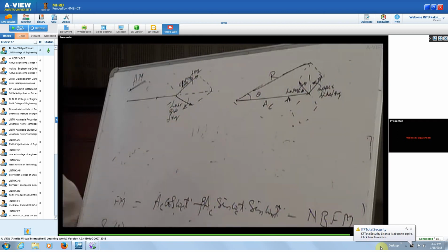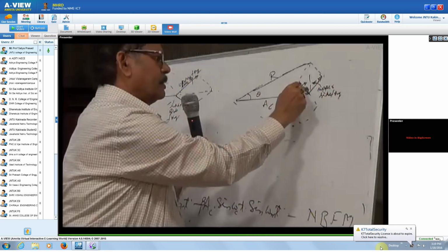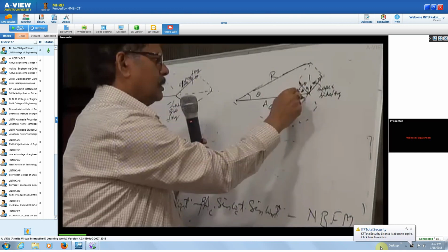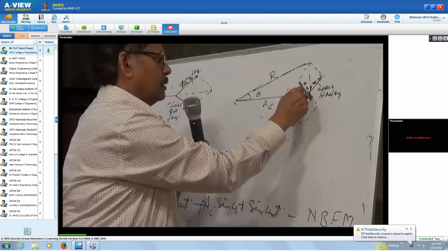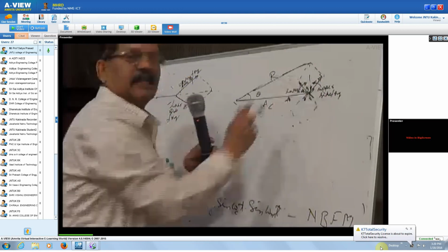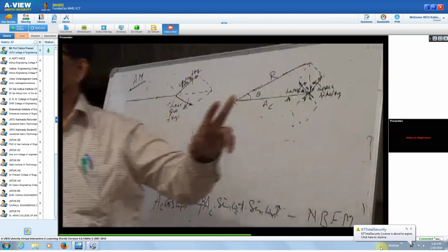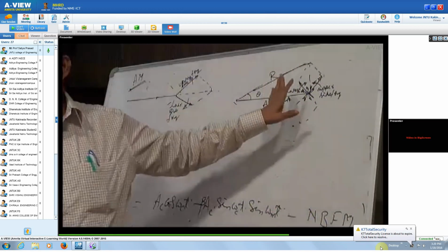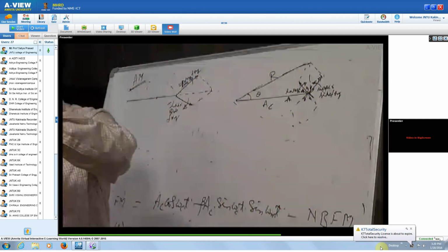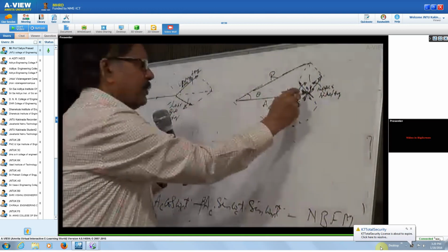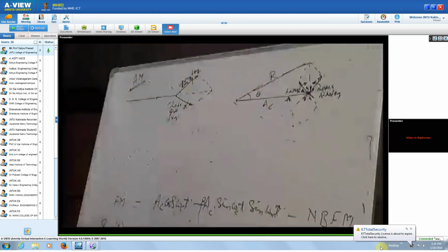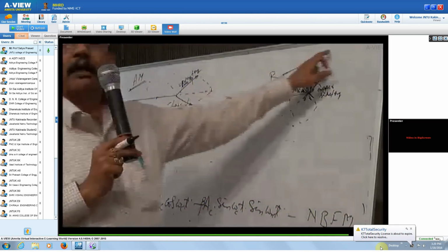How your wideband FM becomes of constant amplitude. So one may be having a number of phasors, beta plus 1 side bands. All these phasors, when they combine together, will be giving you a constant. Right? When you have only one phasor, you are having resultant of different amplitude.